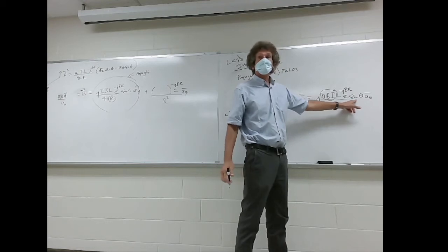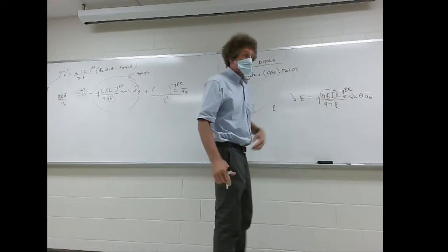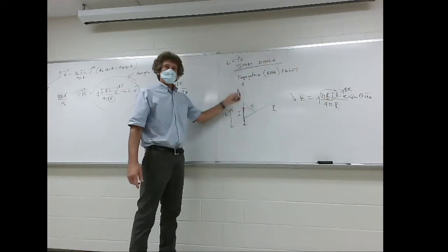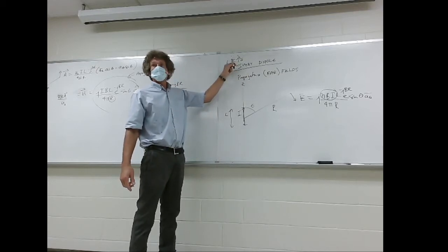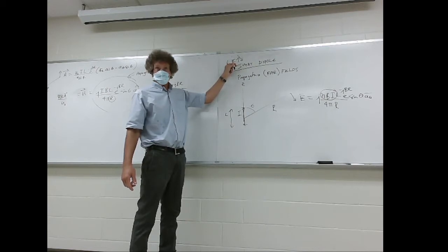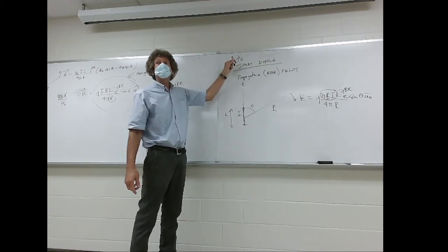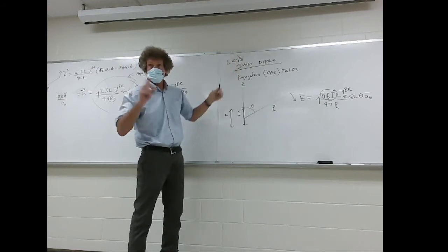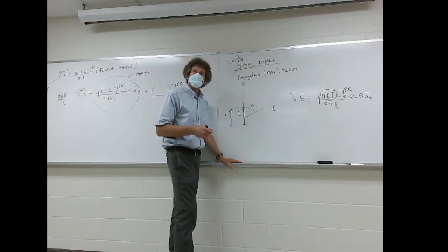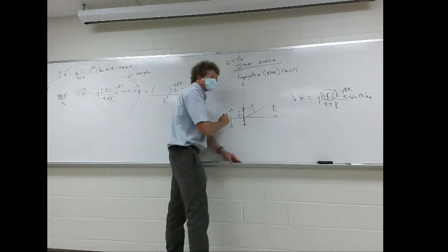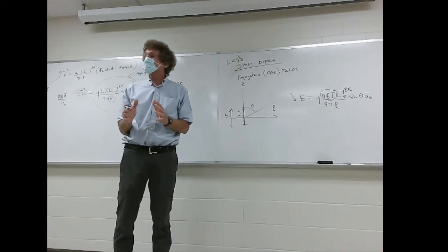Now this is important, because what do you see happening here? Remember, this is the electric field that's propagating, launched. Well, look up here. How much power goes right up the axis? What's the angle if I'm going straight up, class? What's the sine of 0? 0, nothing, right? Nothing propagates in the direction of the current. That's an important concept. Nothing propagates straight down. Where is it a maximum? Yeah, at theta equals 90 degrees, right? It peaks right here. Y'all follow me? As far as the electric field magnitude, we'll get to the power in a second.